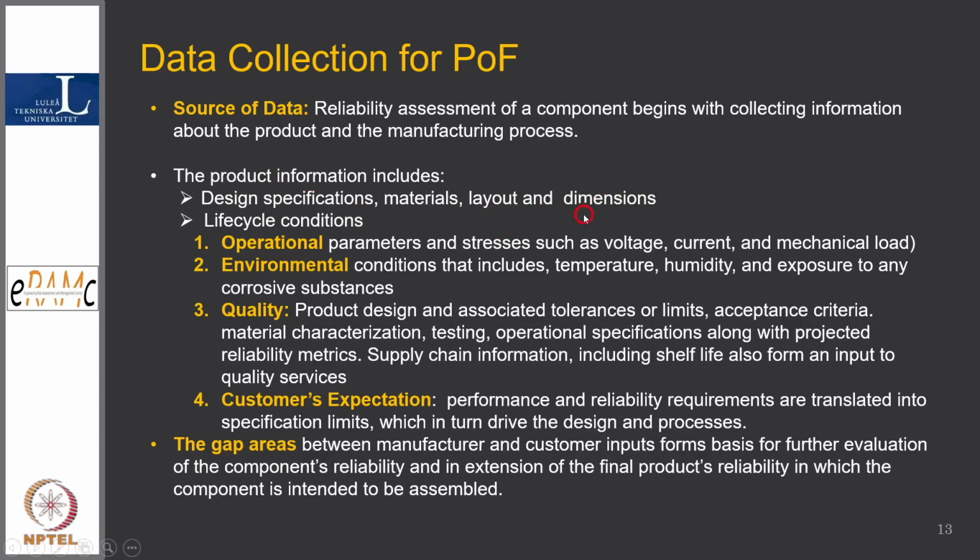For example, if I am designing a system, I must take into account what kind of error a human can make, how he can turn the knob left or right by mistake, how a person can make mistakes in calibration. Even though they are all domain experts, it happens once in a while. What happens if the same oil is added in three parallel redundant system bearings? It will be a common cause failure.